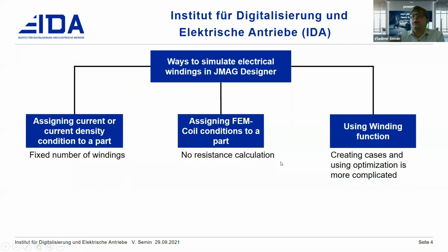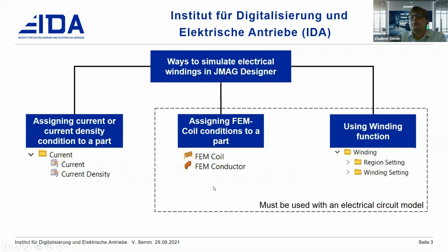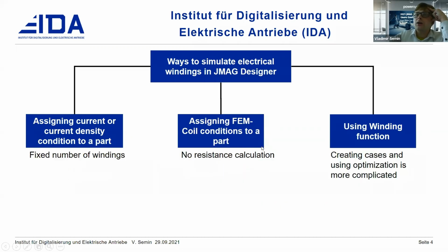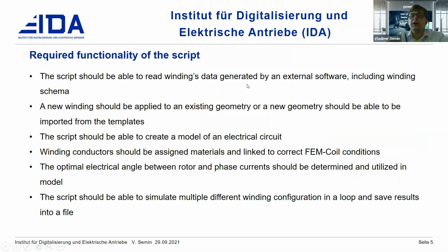In the script I have implemented the method of simulating a winding with a FEM coil. That means that a circuit has to be created automatically, and FEM coils from the circuit have to be linked to the FEM coils and parts in the model.